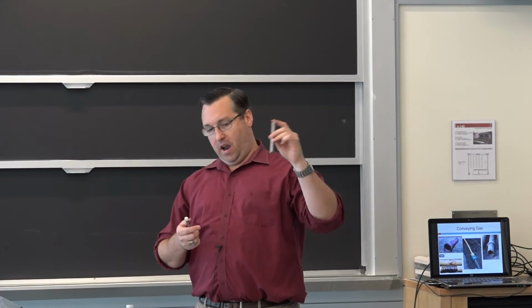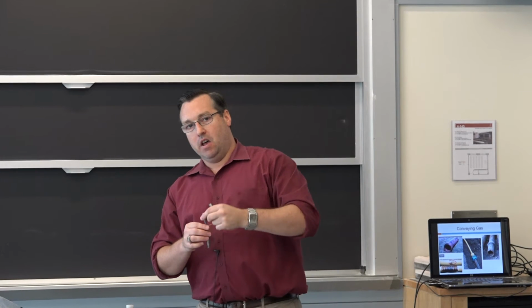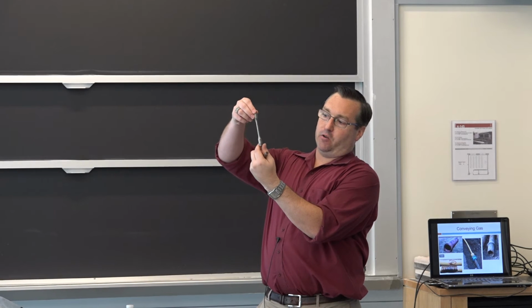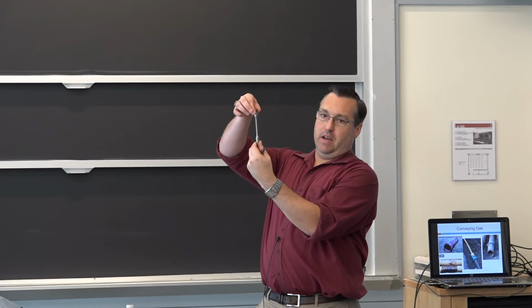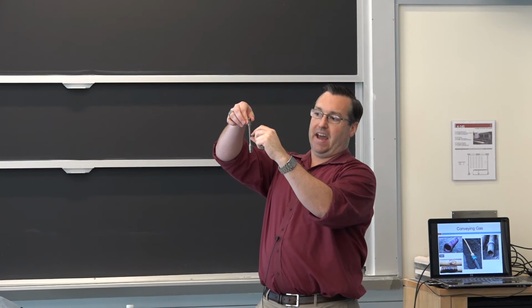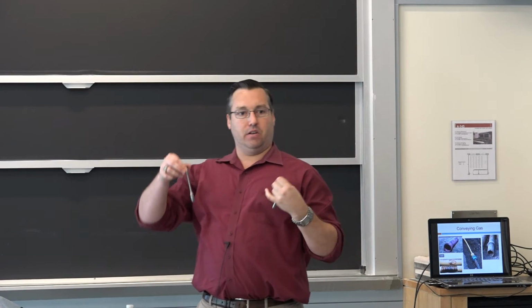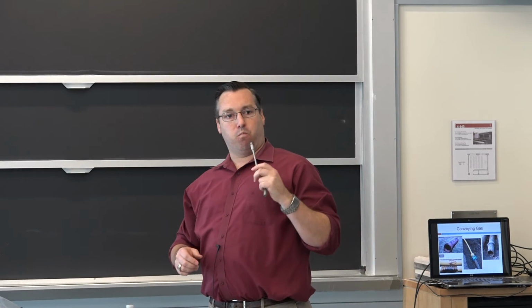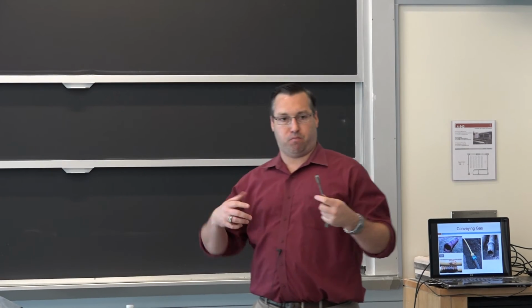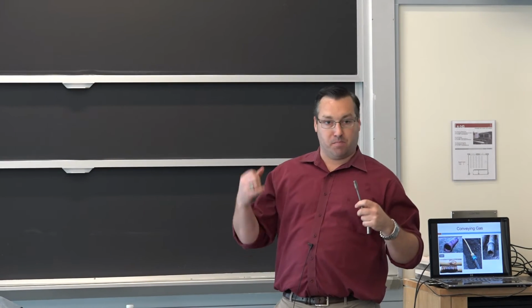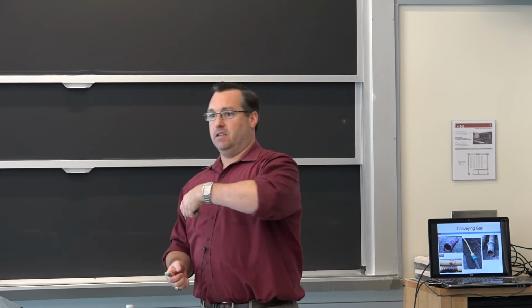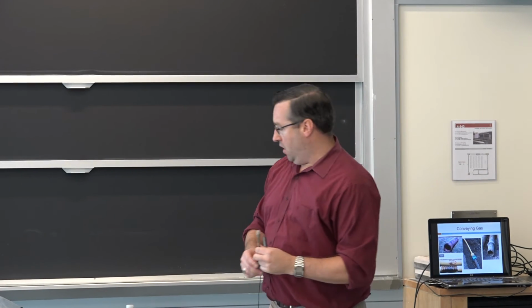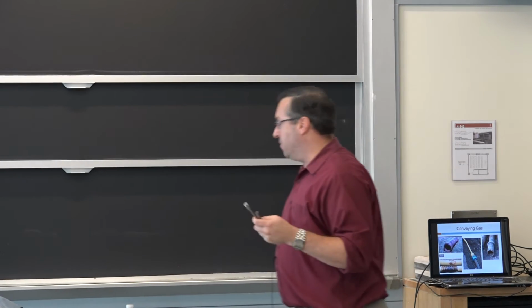This is a blank for a round bar tensile test. So this would go in a testing machine. This gets threaded into grips, this gets threaded into the grips, and you'd pull it, and it will neck down over time, and it'll tell you what your tensile strength and your yield strength is, to tell you if the raw material, once it's fully fabricated, is as strong as it's supposed to be. So for any skyscraper or any large structure, you want to test the metal to make sure the quality of it is what it should be.